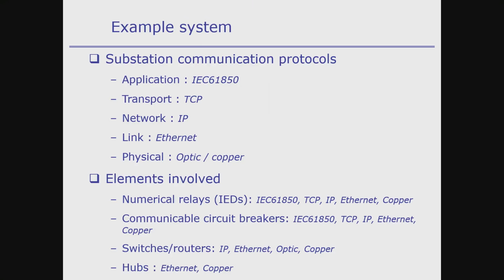Can I use this? So let's say this is your voltage, right? This is time, and this is the magnitude of the voltage, for example. And you are here in time, okay? So you will sample this value, convert it into a digital number, and put it on the network. Then you advance in time, you are here now. You will sample this value and put it on the network. It's one value at a time, but you want to do this as quickly as possible because this value is needed by the relay IED, which runs the algorithm using this sample and maybe previous samples. So you can't afford to wait, right? You understand? Yeah.